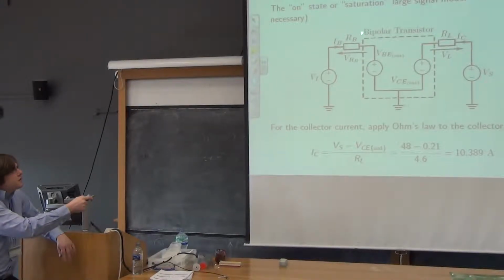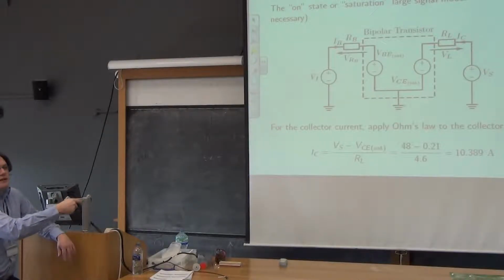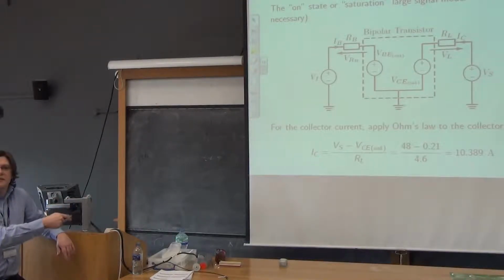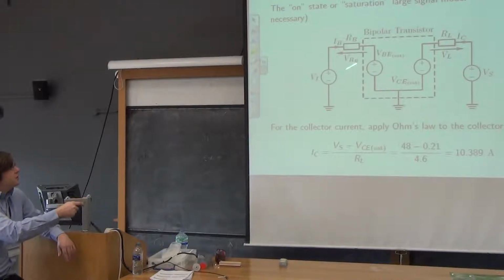There is no way that current can flow from these three components towards these three components. And the reason is the only way that current can flow is, let's just say for the sake of argument, down through VBE, along ground, and then up through VCE. Fair enough. But how will it get back? There must be another mechanism for it to travel back. You can't have a circuit of just one wire. You have to have a loop for currents to flow in. So all this stuff can be ignored, and we only worry about this business here.